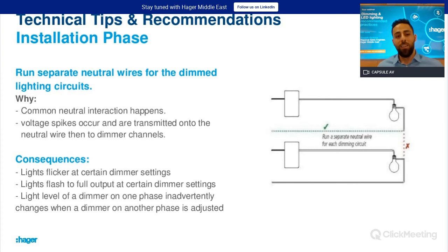One of the important points is the neutral wire for lighting circuits, not on the dimmer side but at the lighting level. A lot of fights happen over this. The contractor does not want to install a separate neutral for every wire. From his point of view, we understand, because he needs to not increase his cost. He's paying this from his pocket. They sometimes take a lump sum.